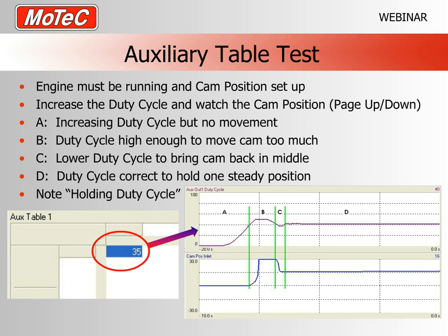You should be able to hear this in the engine's note. So if you're moving the camshaft at idle, you're going to be able to hear it in the note of the engine. You might have to be a bit careful, because it might be a little bit too much advanced and it might stall the engine. So maybe you want to do this with a bit of throttle. So that's no good. It's fully against a stop.